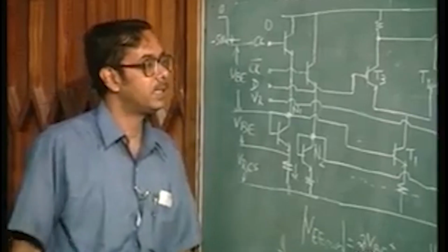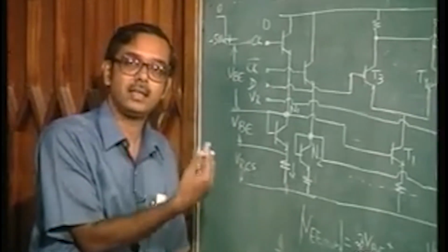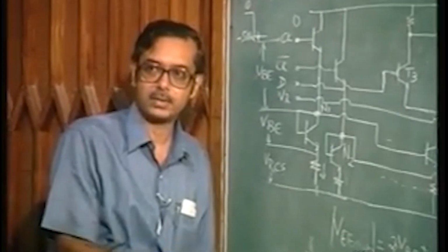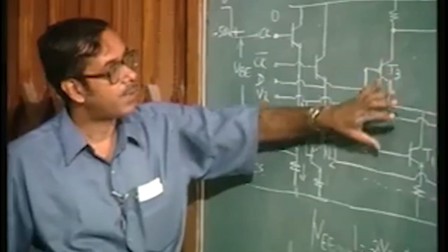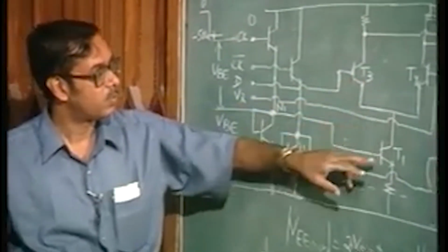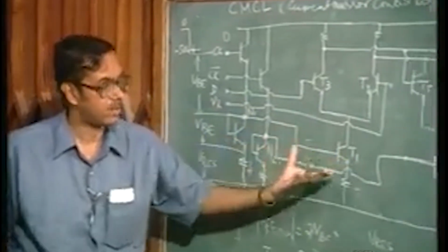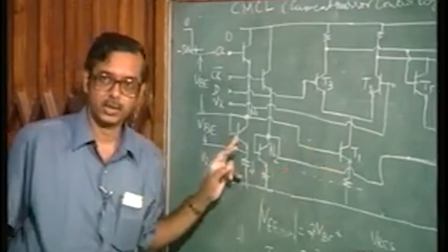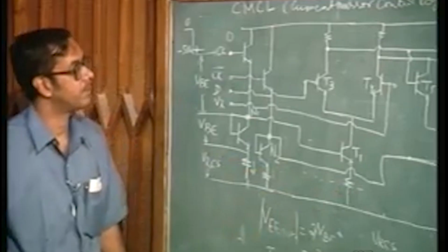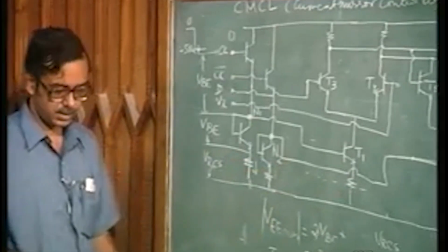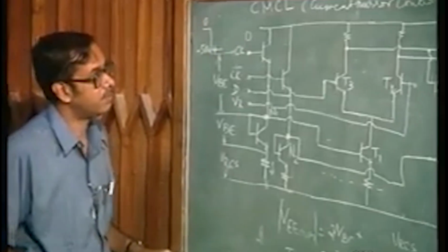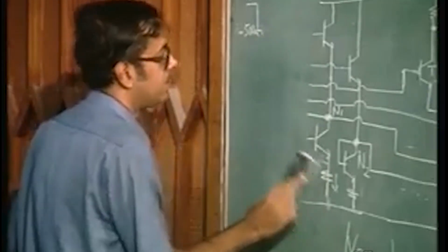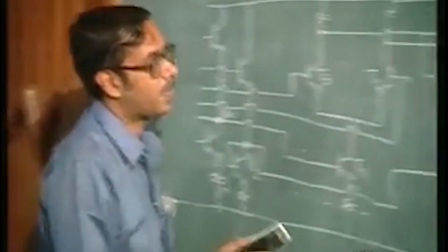All right. So, in fact, this is a D flip flop. Using the same concept here, one can actually realize other logic circuits also, just like a 2-level stack. You can realize other logic circuits where the lower level is actually controlled not by an emitter coupled structure, but by a current mirror arrangement, as given here. I will just give an example. I will quickly modify this. It is easy for me to do on the blackboard.